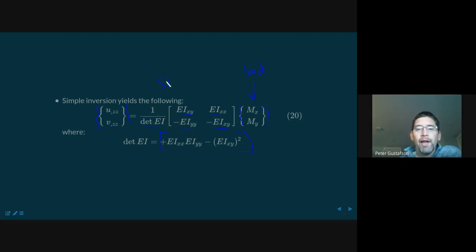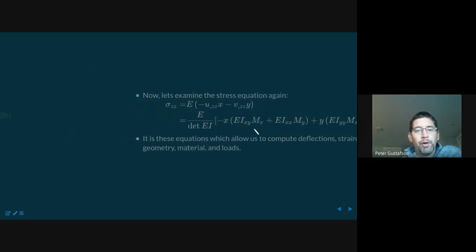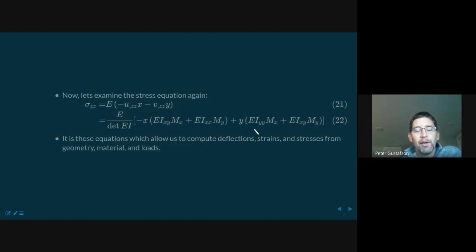This column here can be thought of as, sort of, compliance, really, is what it is. I was writing stiffness, but this is compliance. It's a matrix term, and it represents the material and geometric, so material plus geometry. And then this over here, as I mentioned, was displacement, second derivative of it, but important. Okay, so now everything's starting to make a little sense. It actually isn't too difficult because the 2x2 matrix is really easy. You guys can integrate, the integration Ix, Ixy, Iy, those were all pretty easy area integrals to do, no problem. And of course, in the last 3 or 4 slides, we finally related these moments to the distributed load. So here we're going to go ahead and deal with that in another couple of slides.